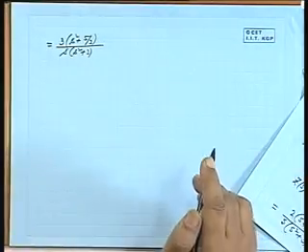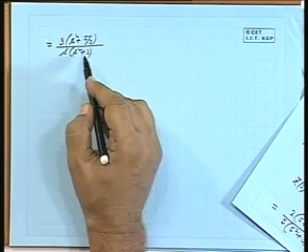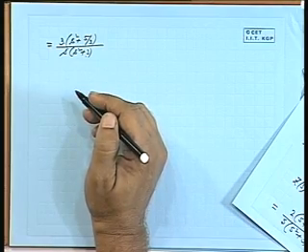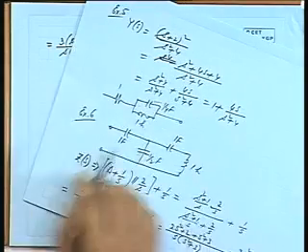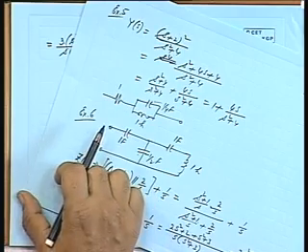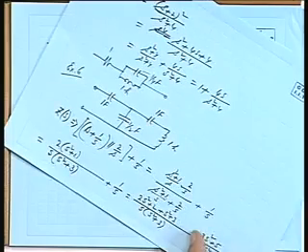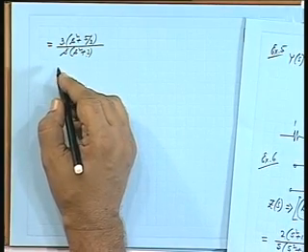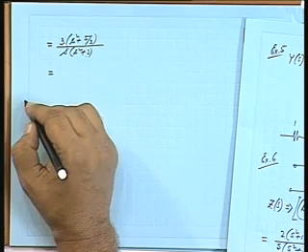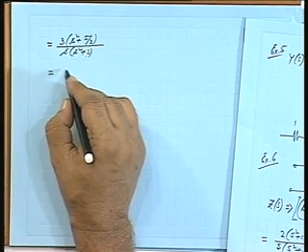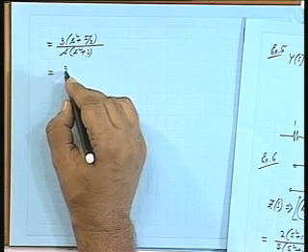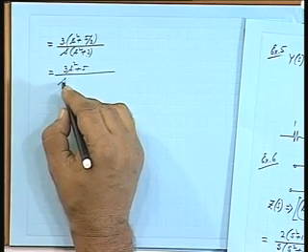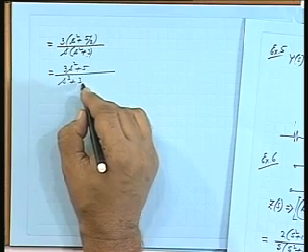Now, you see how many elements are there? 1, 2, 3. You can realize, if you want to realize by the same type of network, alright, that is Cauer synthesis. So, I will write (3s squared plus 5) divided by (s cubed plus 3s).